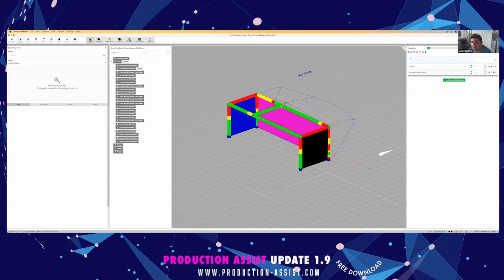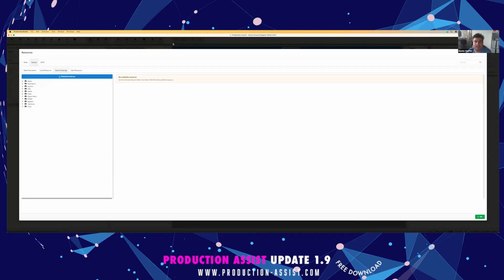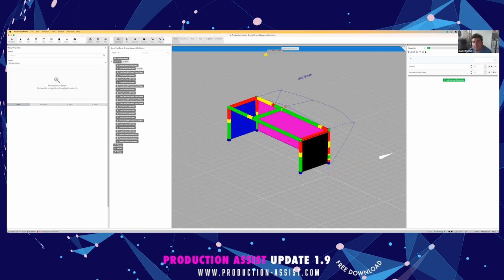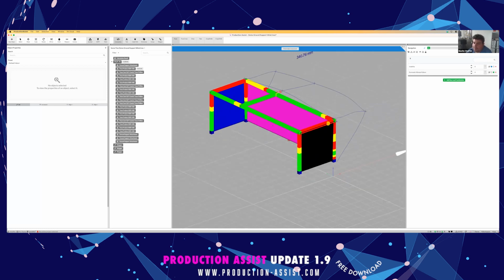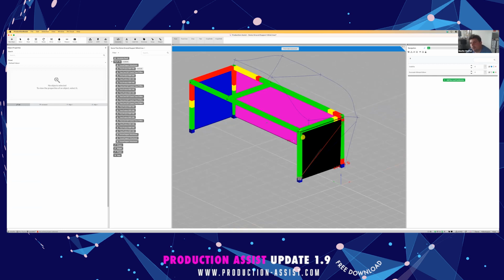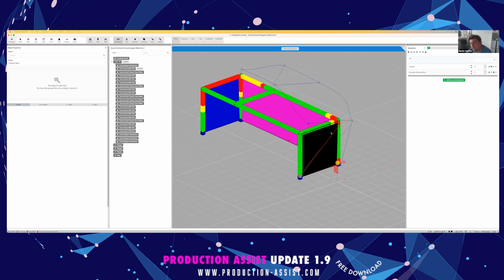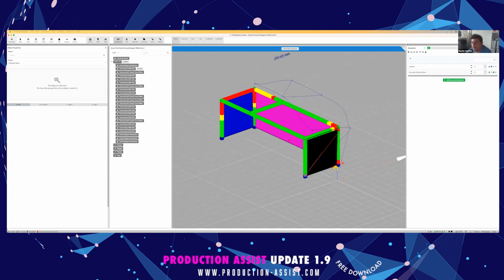So how to fix this? For this, it's really easy. What you need to do is put in a rope. So when you go to a new object, go to the connections, use a rope, and put the rope in there so that it's releasing pressure from the system. You can do this, and you see it changes the calculation. So this corner now looks better. You still have a little bit of problems, so what you now need to do is put in a pipe or something that releases a little bit of the stress. But that goes too much into detail right now.